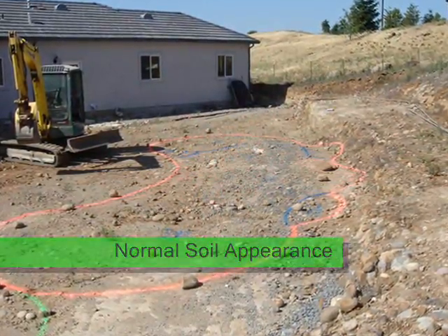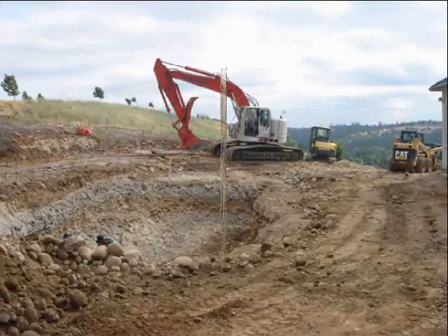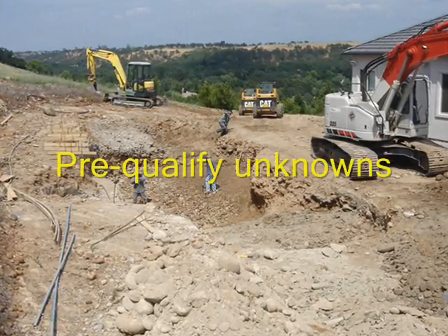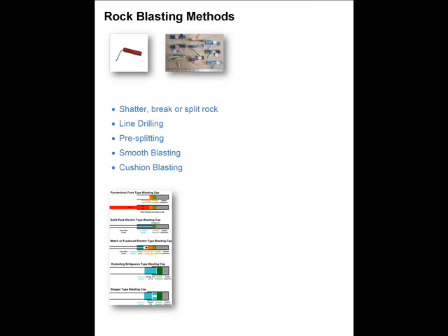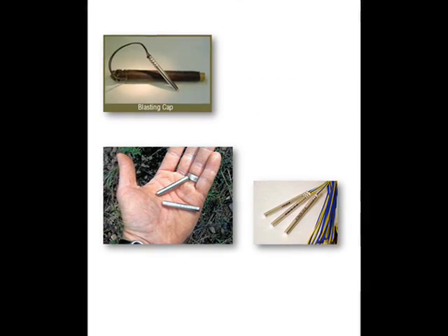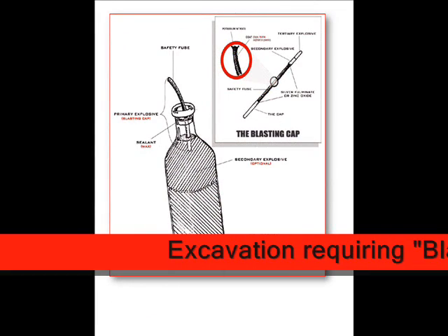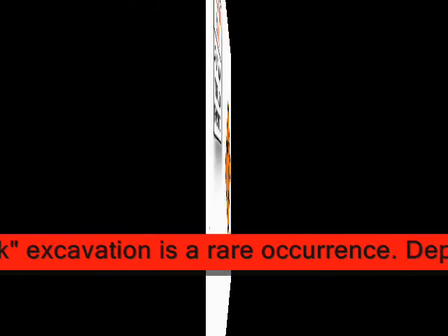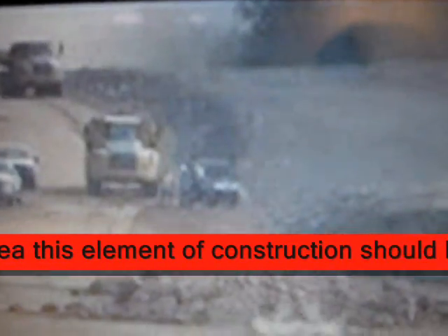Understanding the soil's composition will help you to better understand the work scope and also better qualify what is to be made inclusive, or what is unknown and is being identified as an exclusion. As an example, excavation of rock subsoil strata where blasting is required will result in essentially excavating to the level of the rock, making blasting preparations, covering the rock sufficiently with a thick layer of bedded soil, and then detonating the explosive charge.